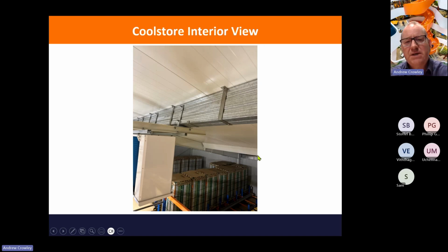Here is a detail of the underside of the roof. So here is our toe-to-toe channels forming a box section, and that acts as the purlin. So the SIPS panel sits on top of that with through bolts in there. So you'll see this particular building is in operation as we have pallets and pallets of fruit being chilled in the cool room.